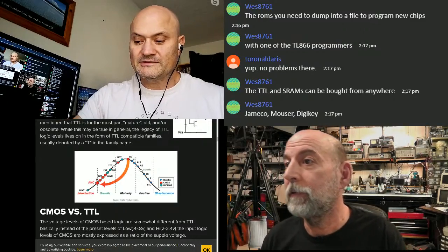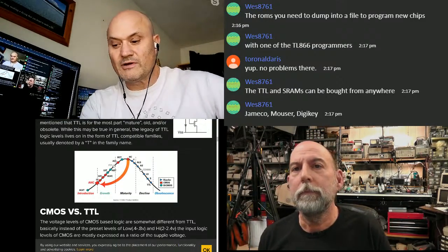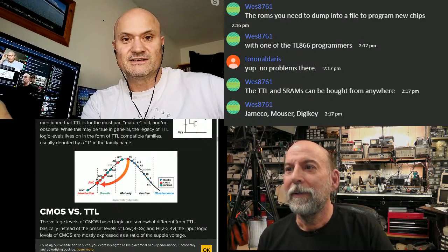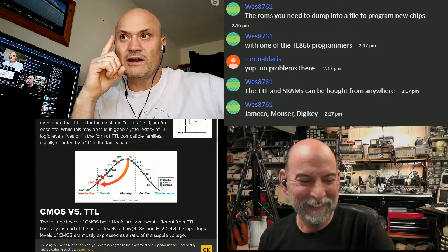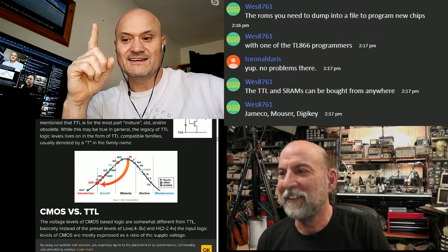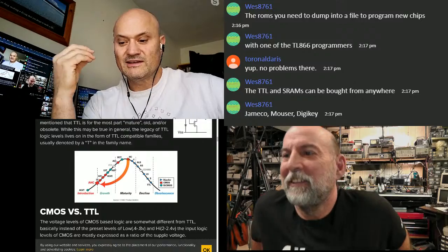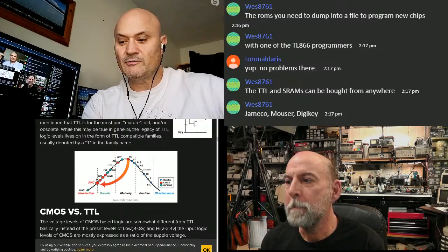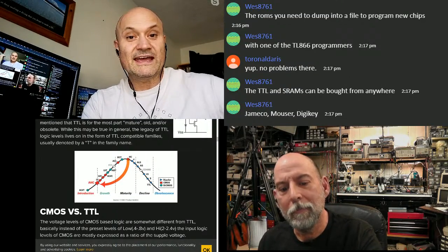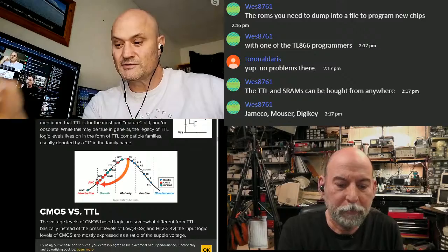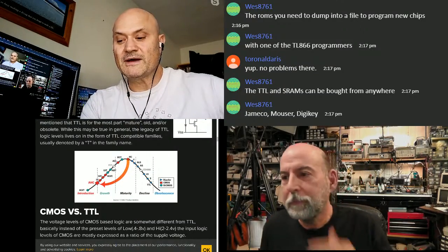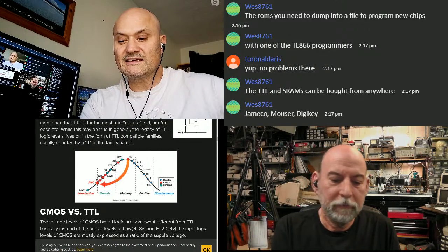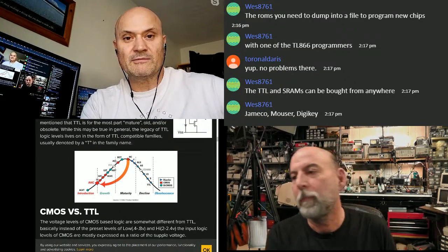And there was a white paper put out some time ago by Xilinx on how to build a delta sigma D to A converter just in VHDL. Right. You take up one pin on your CPLD or FPGA, and you've got a high fidelity analog output. All you need is a low pass filter, and then any other kind of amplification that you might want after that. And you've got a really high quality analog output that'll go from DC to probably 1/100th of your main clock frequency going into it. Right. So it's a pretty useful technique if you have programmable logic as well.